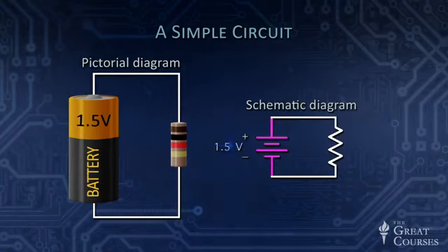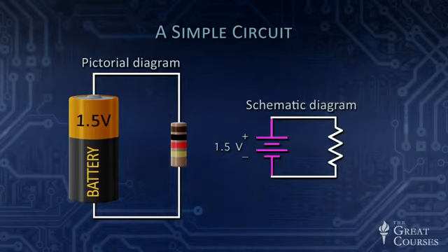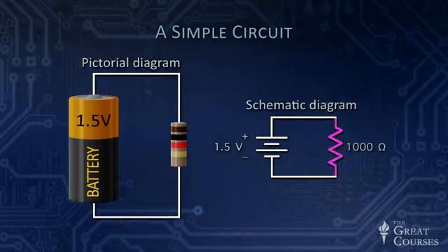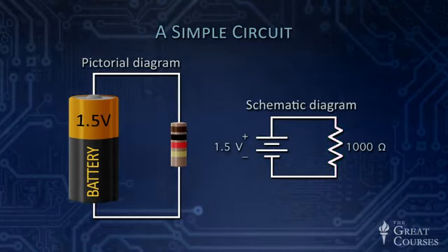It's a 1.5 volt battery. Remember, a volt is a measure of the push that that source can supply in terms of pushing current through the circuit. And on the right-hand side, you can see connected directly across the battery is the 1,000 ohm resistor, as represented by that zigzag kind of symbol. So there is about the simplest circuit you could imagine making.